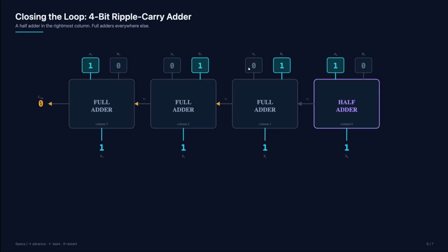All right, so you can flip the bits here and see what happens with the different situations. Like I'm going to flip this bit and you see the carry out lights up and it goes to the next stage, which forces that to carry out. As you play with this, that's what you should do. Play around with this and make sure that you understand that it takes steps for this carry to propagate through to the output. You have to start over here at the right and move your way to the left. And if you had a 16-bit adder or a 64-bit adder, this would take significantly longer because there's a lot more to that ripple process.